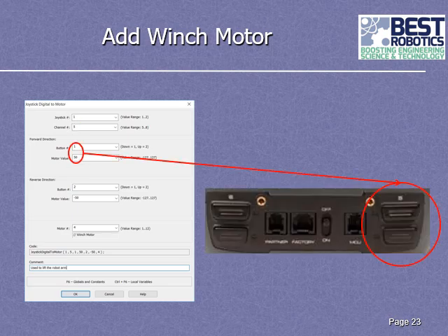So as you can see, the button number 1 equates to, says down. If you look really closely, you'll see a U and a D on those 2 different buttons. There's an up button and a down button. The first button we're going to configure is number 1, which is the down button. And for this one, we're going to tell the motor to move at a rate of 50.